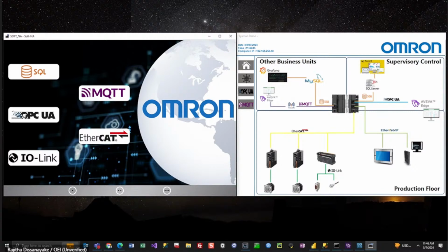Okay. So in short, NJ and NX controllers that have the suffix 20 indicate that there is OPC UA built in. So let's look at the NX102-1220. That unit would have OPC UA, while the NX102-1200 would not. However, the NX502 kind of breaks that mold, where there is no suffix for 20, yet all NX502s have OPC UA as standard.